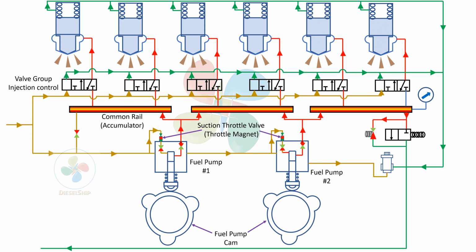Right. And then the fuel injector is a mere fuel injector. If the pressure is above a certain bar, it will open, inject, and atomize the fuel, and then when the pressure goes down, it will close due to the spring force, right? And then the flushing valve. The flushing valve is one of the main valves that aids fuel circulation. When the engine is running, this valve is closed, right? When the engine is stopped, this valve is open. So it aids the fuel circulation. The yellow or brown line to the green line is connected through a flushing valve. So the flushing valve is very important, right? The next one is the safety valve. Okay, any pressure vessel has to have a safety valve.